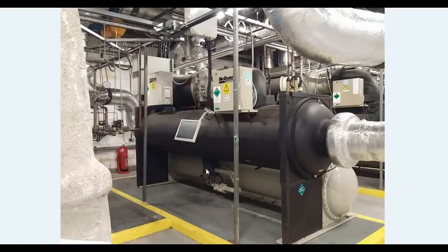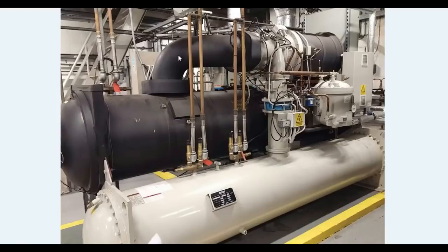So that is entering into the expansion valve, which expands the refrigerant and allows the refrigerant, when it enters here into the evaporator, to pick up a bit more heat where it passes through this tube at the back there, passes through here, enters into the compressor.